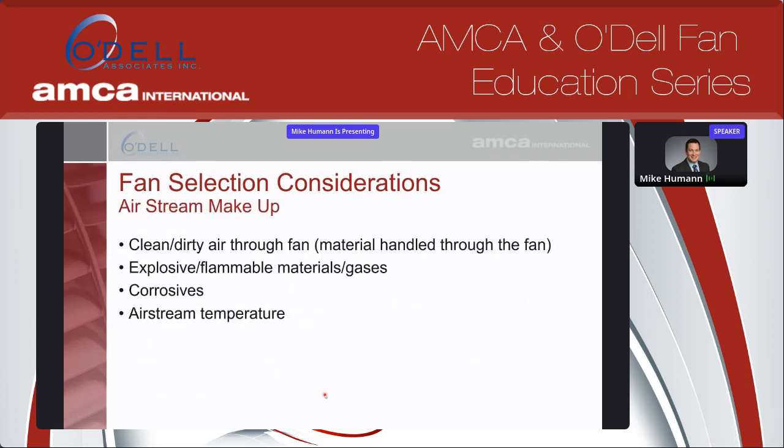So, some other considerations: we certainly want to talk about airstream makeup, and that's critical to help select the best fan, and the fan that's going to be able to handle the application and have some longevity, versus incorrectly selecting a fan where you could have some potential issues. A couple of those: is the application clean or dirty? What is the airstream handling? Is there particulate in the airstream? Is it just clean, ambient air? That's certainly going to change the direction of your fan selection.